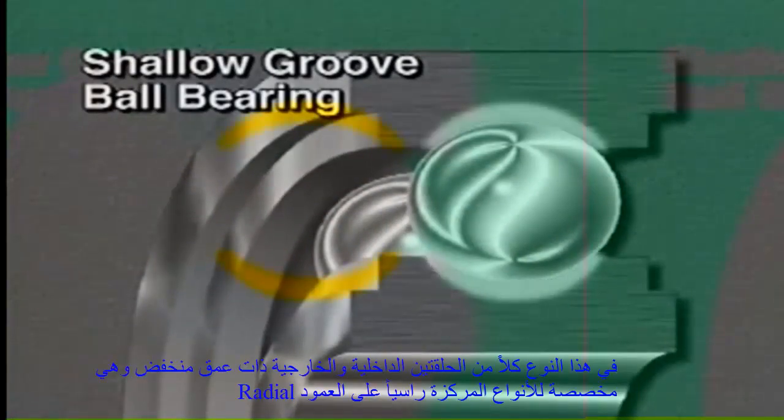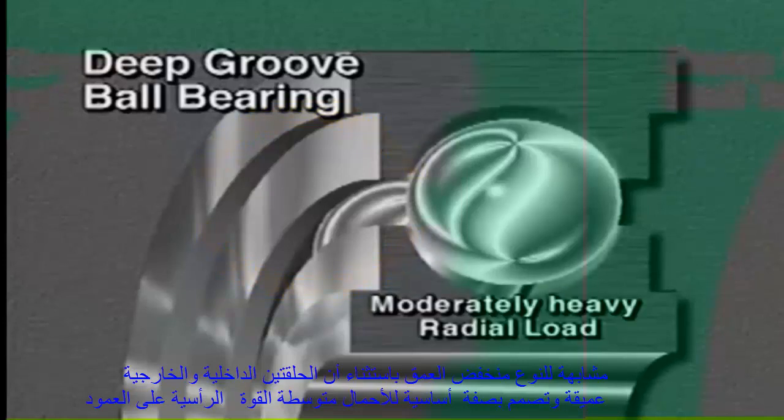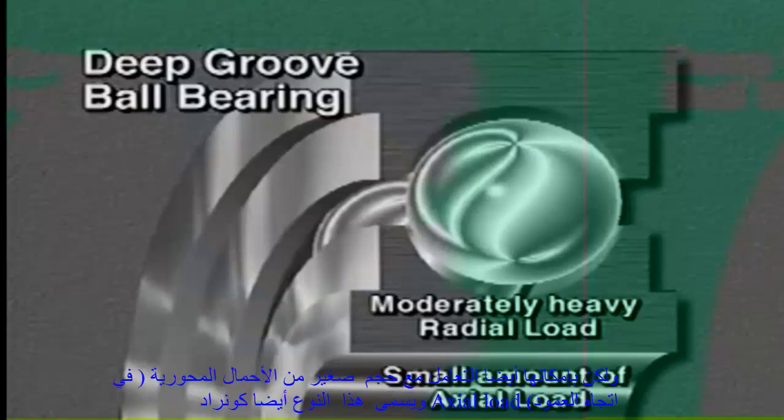This ball bearing is a shallow groove ball bearing. In a shallow groove ball bearing, the inside surfaces of both the inner and outer rings are shallow. This type of bearing is specifically designed to handle radial loads. A deep groove ball bearing is similar to a shallow groove ball bearing, except that the inside surfaces of the inner and outer rings are deep. Deep groove ball bearings are designed primarily for moderately heavy radial loads, but they can also handle a small amount of axial load. This type of bearing is also called a Conrad bearing.